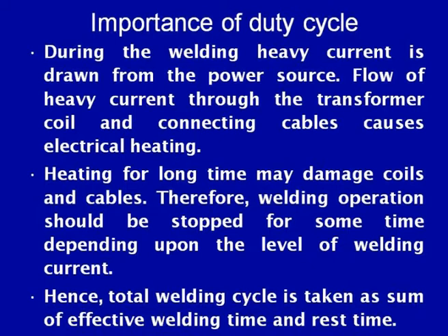We know that during welding, heavy current is drawn from the power source, and the flow of the heavy current through the transformers, coils and connecting cables causes electrical resistance heating. Heating of the coils for a long time may damage the coils and cables. Therefore, welding operations should be stopped for some time depending upon the level of the current.